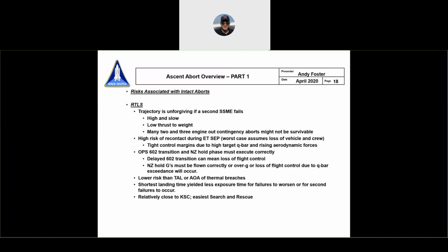And where you really saw that was when you trained people or you went out and you flew a manual RTLS, and especially in the pitch down. If you did not have the side slip angle totally zero, and you're holding it there at alpha -2 and trying to get the tank off or waiting for the tank to set, if you've got any beta or side slip at all, it'll start rolling off on you. And so then it's a matter of, can you square that away, or does the system get the tank off fast enough to help you? Or if you really want to, this could go either way. You could try to manually fast step it and get off. But that was absolutely the diciest part of the whole thing.